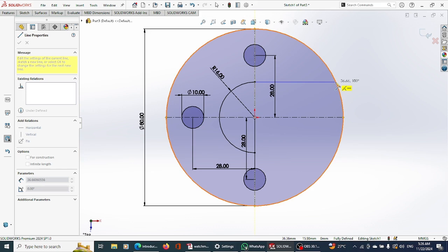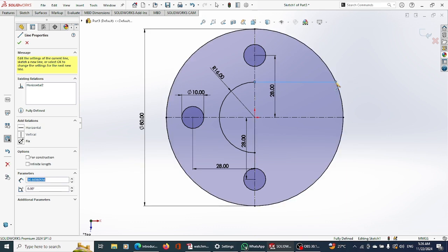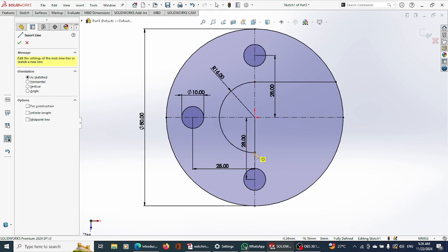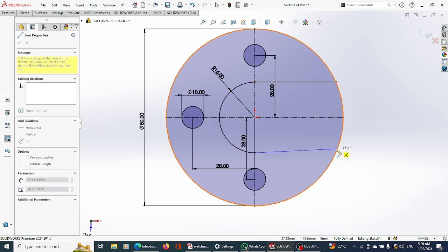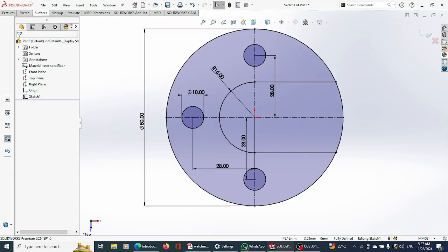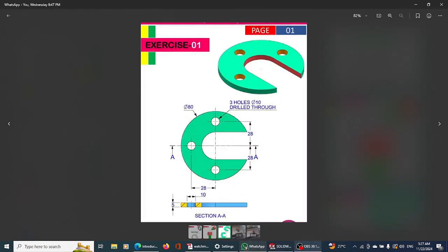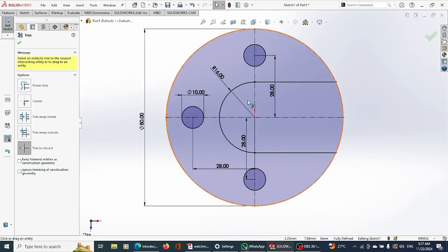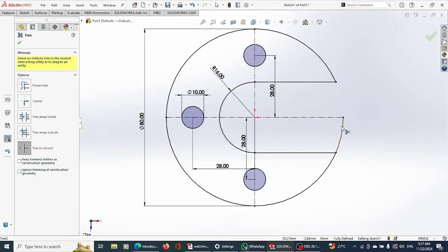That's what it means. So SolidWorks is easy. So I click, my line still continues. I just hit escape, I hit enter, come back here, do the same thing, then escape. Now I simply need to come and trim. I want to trim this guy and this guy away, so that it looks like this. Good. Now I'll go to sketch, I'll go to trim entities. I'm already on trim to closest, so I'll just go here, trim this guy and trim this guy.